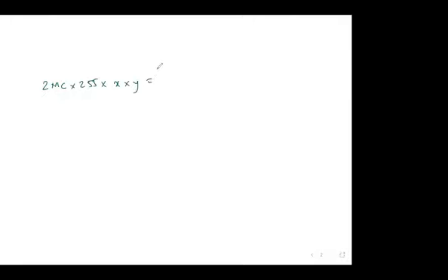It should be, okay, sorry. Then it will be multiplied by your time period, say 0.85, whatever the time period is. This should be equal to the exact time delay that you want to generate. Say you need to generate 25 microseconds. So now you need to find the value of X and Y. You can choose any value of X and Y as long as this calculation gives you a result which is approximately equal to 25 microseconds.